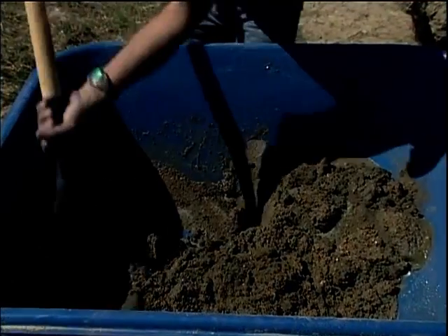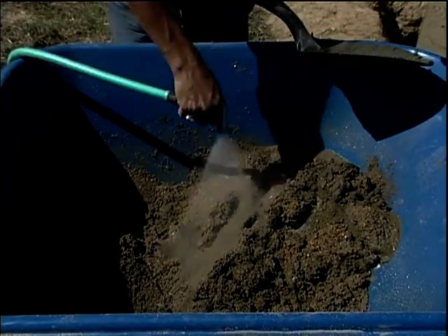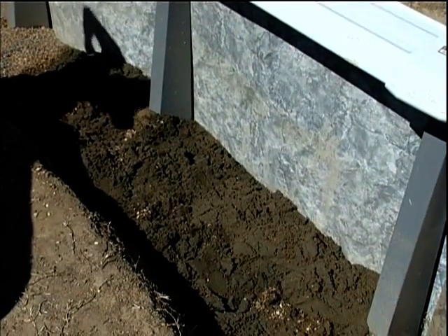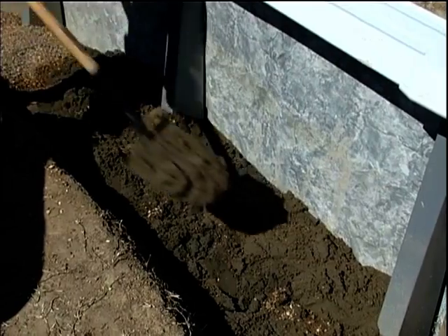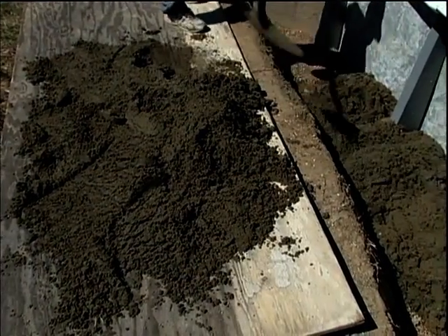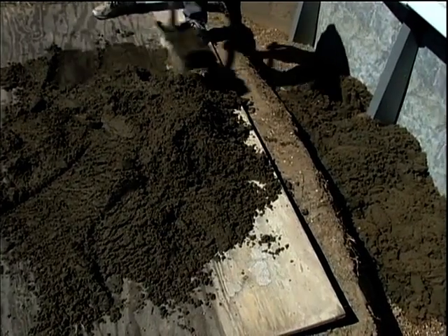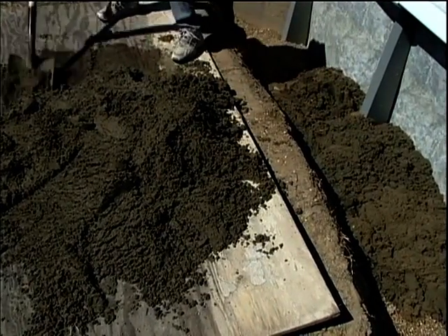The second method is to mix the sand, gravel, and water before shoveling it into the area around the pool. Never pour the slurry mix directly from the truck into the backfill area. Shovel the mix from a wheelbarrow or dump the mix onto a flat wood surface and then shovel into the pool backfill area. Controlling the composition and application of the slurry mix is key.